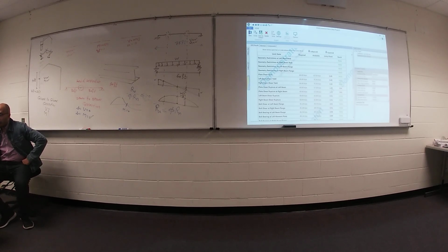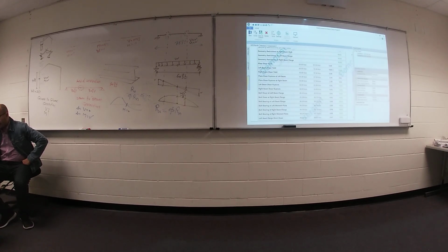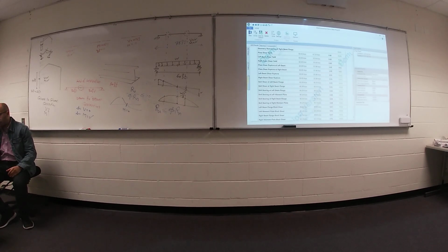It fails with only 0.05, so almost. As you see, one more time, if this number is smaller than 1, you are safe. The smaller than 1, the safer. Like this one, 0.47, more safe. Like this one, 0.91, perfect. Between 0.9 and 1 or 0.99 will be good.